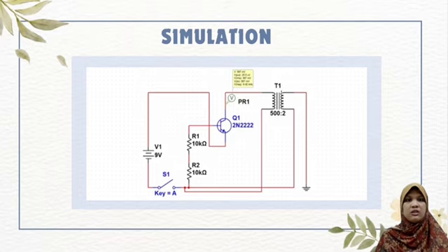The circuit includes a step-down transformer with a turn ratio of 500 to 2. If you look at the image, the voltage across the transformer is quite small, which is 397 mV, which results in a high current exceeding 1 ampere. This current exceeds the transistor's maximum rating, which leads to overheating.